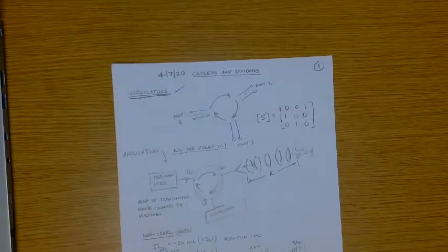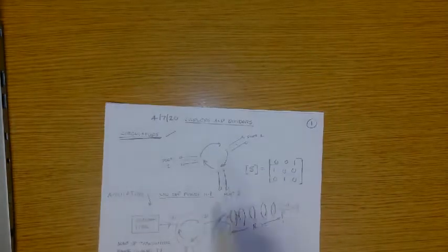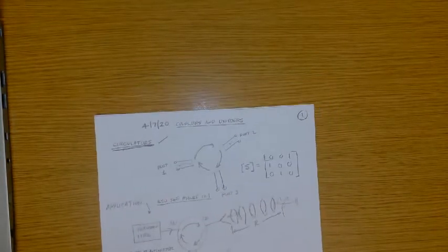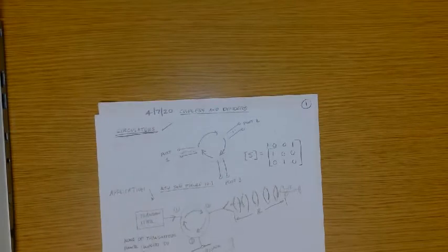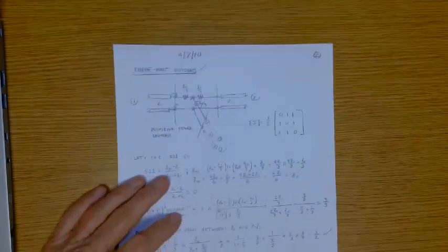So if you're trying to buy a circulator for X band, then you'd have to look at the device parameters as a function of frequency over the range of frequencies from 8 to 12 gig. That's X band. Might be a radar application.